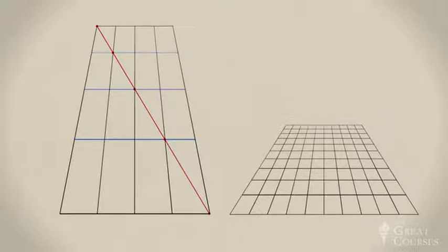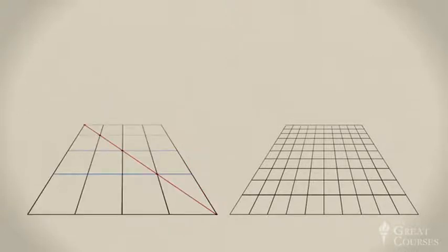To isolate the effect of the number of divisions on the ground line, let's use identical floor planes. Same thing, though less pronounced. Whatever the degree of foreshortening of the original plane, fewer divisions along the axis or ground line will result in less foreshortened grid units. More divisions, more foreshortening. So, if I had 20 divisions along the ground line, the individual grid units would all be even more foreshortened. Here's the point. I want my receding grid units to look like receding squares.